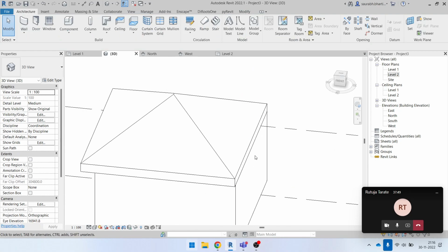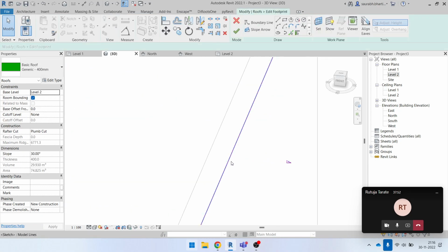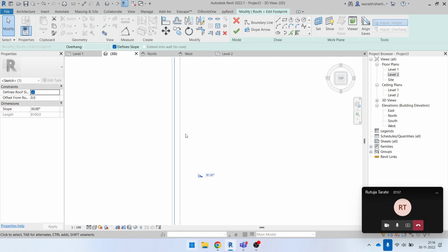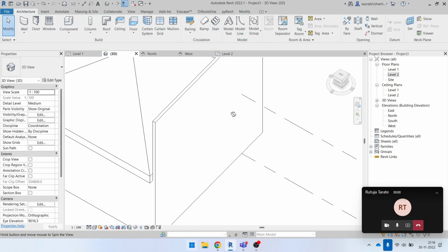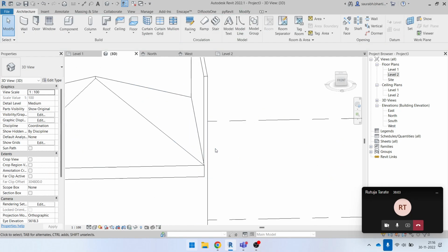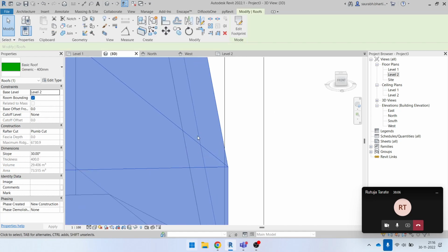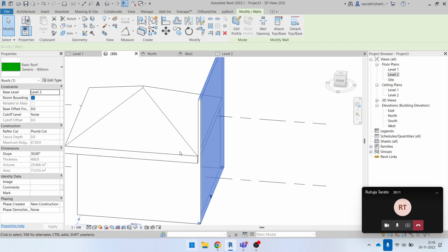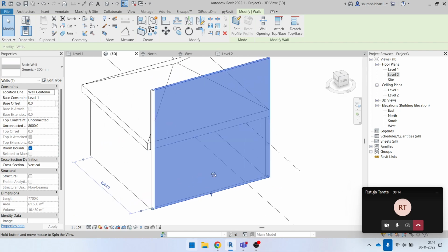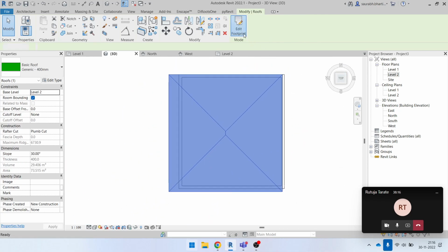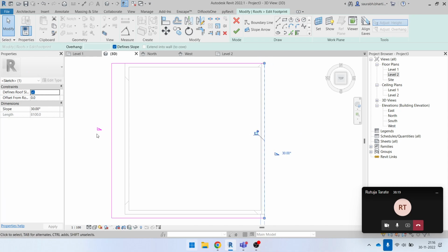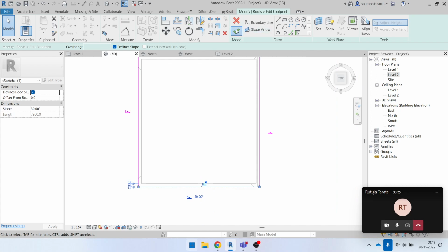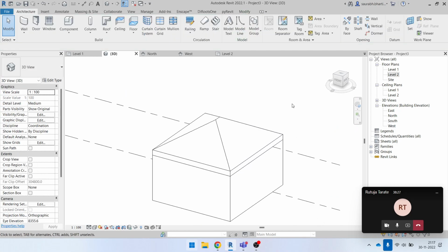Now you can see this is attached, but in case it is a little bit on the inner side, something like this is just half away of that wall, so a layer of the wall would come up like this. In this case, now you can see that half layer that we left over here. Can you see this half layer? This is underneath that roof, but the half layer that is not covered by that roof is coming outside. So you always have to remember that you have to make a roof or a ceiling that is exactly on the point, or on par with the walls, so that it can attach with the roof. Okay,